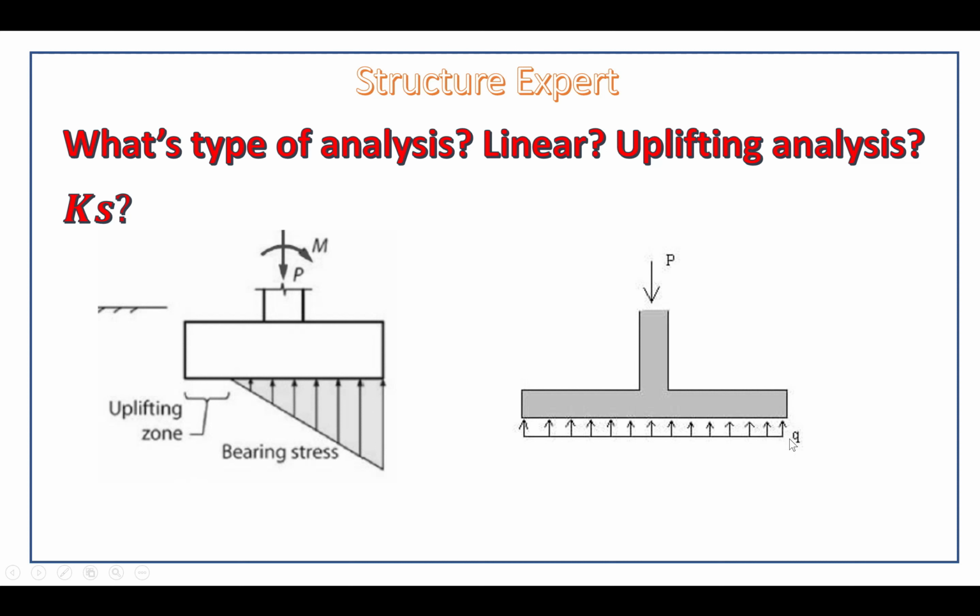So with the axial load, the area is fully distributed at the base. In the case where we apply the load with eccentricity or with an applied moment, the bearing stress at the base is not in full contact with the footing. We have the compression, and this one is the uplift. So how can you perform analysis in each case? We will discuss it in the next slide.